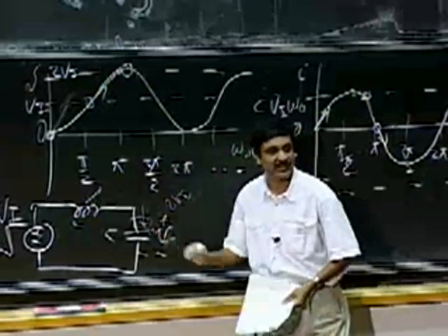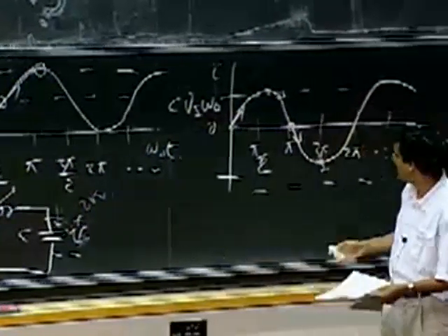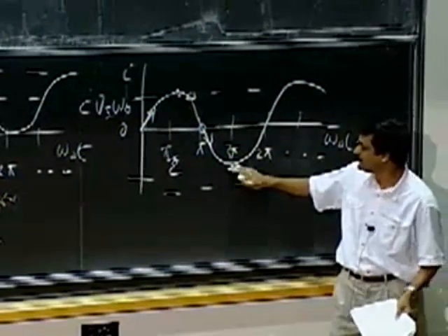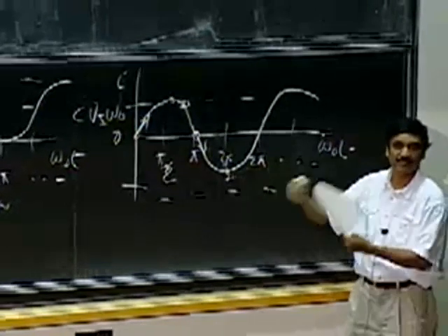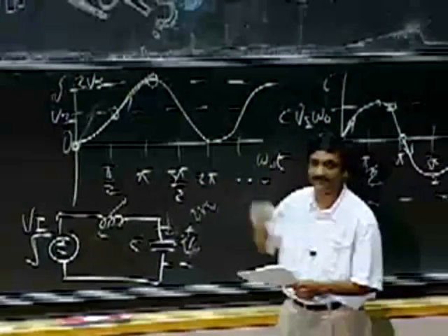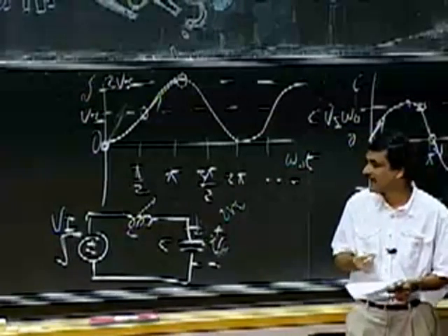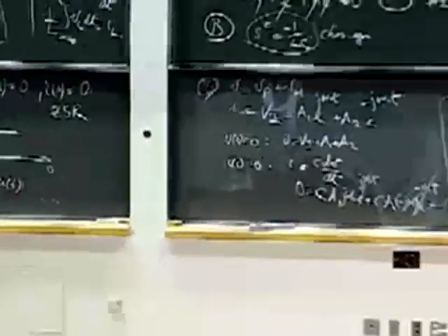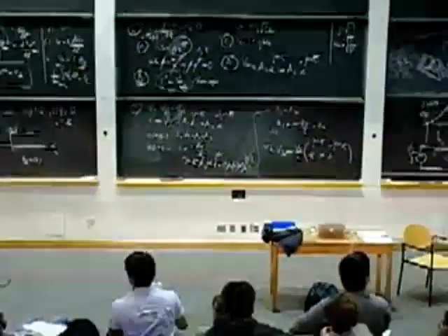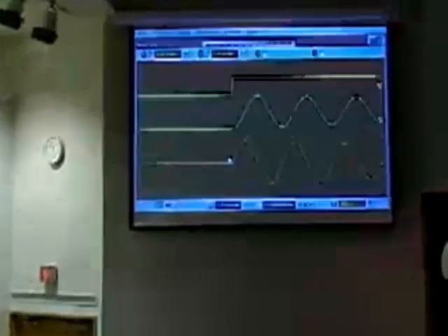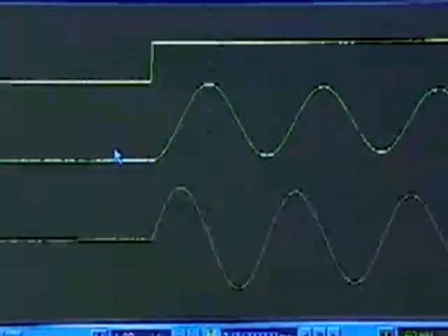So that begins to discharge the capacitor. And the current then goes down to a maximum negative current, and this process continues. So what you're seeing here is energy sloshing back and forth between the two, and that's kind of a key. I'll just quickly put up a demo that you can watch as you're walking out. So for a step input, notice the green is the voltage across the capacitor, and the orange is the current through the capacitor.